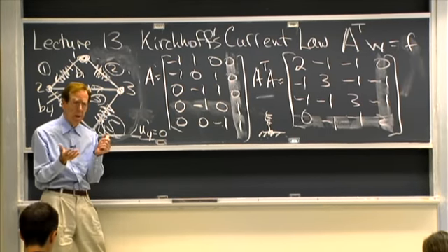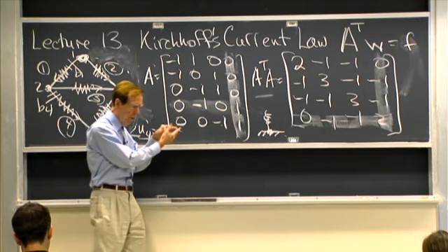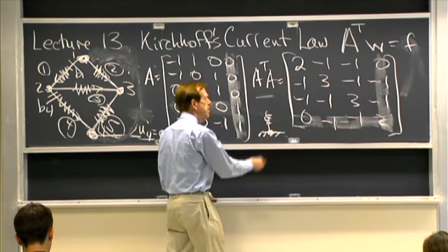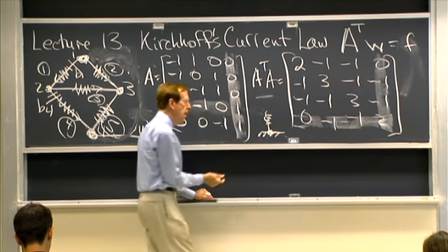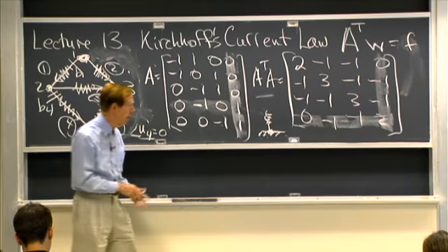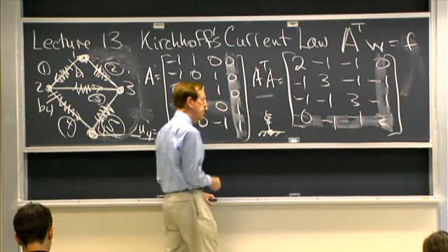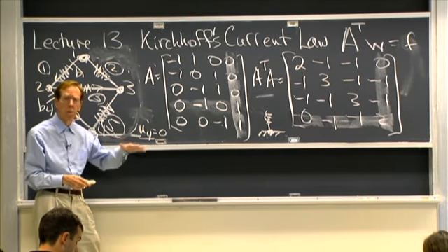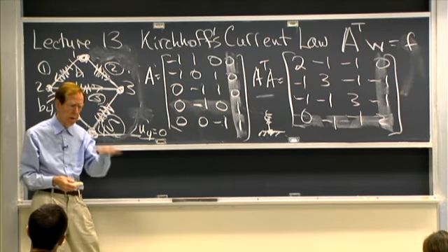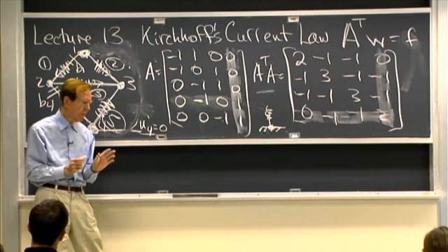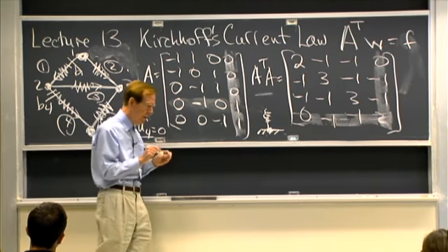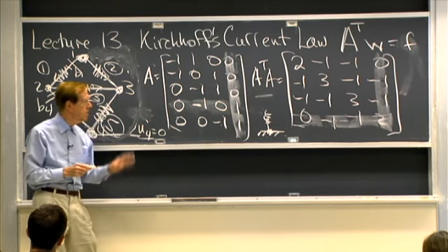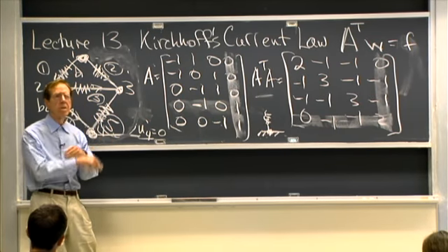And so I solved the fixed problems for all the other displacements and all the spring forces. And then I could come back at the end and say, okay, what was the force in that spring, and therefore how much is that support? What's the force being supplied by that support? See what I'm saying? That the force balance at this node comes afterwards.